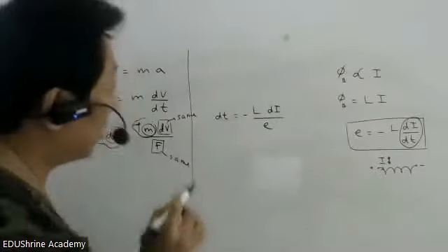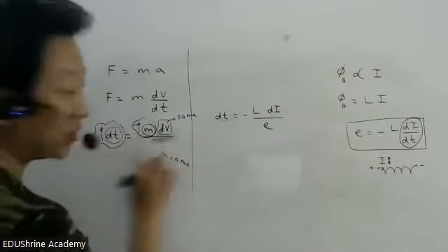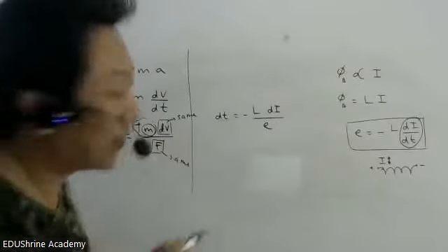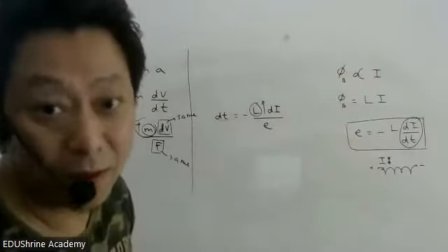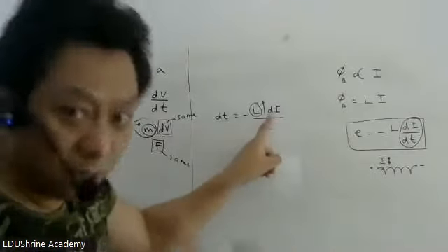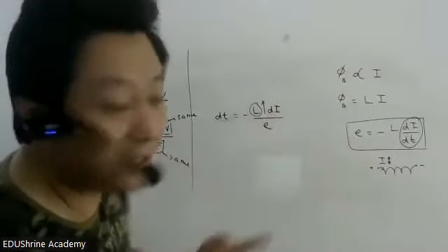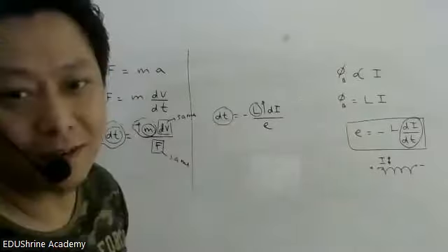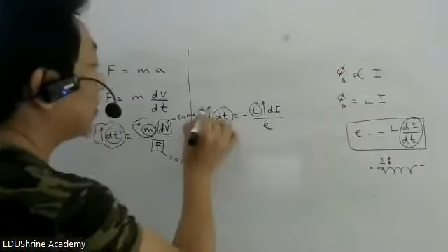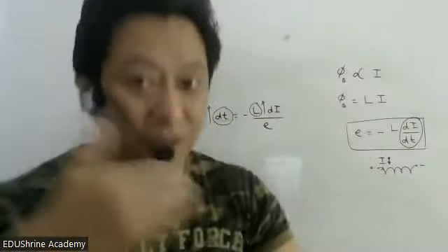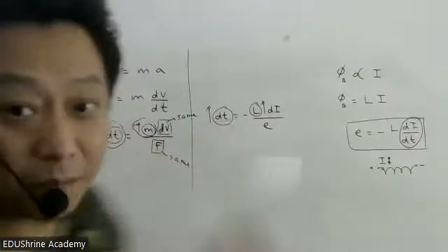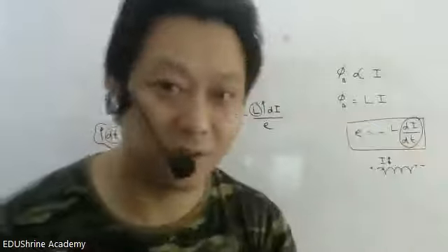Similarly, can I write this formula like this? Now observe carefully here. Similar to this equation you see now. If the inductance of the circuit is more, what does it mean? Your current will change, no doubt. But what does it mean? It will take more time. So that is the meaning of inductance. Inductance basically opposes change in current, just like mass opposes change in velocity.